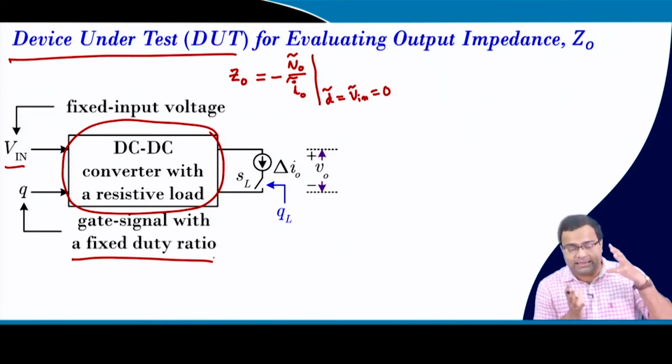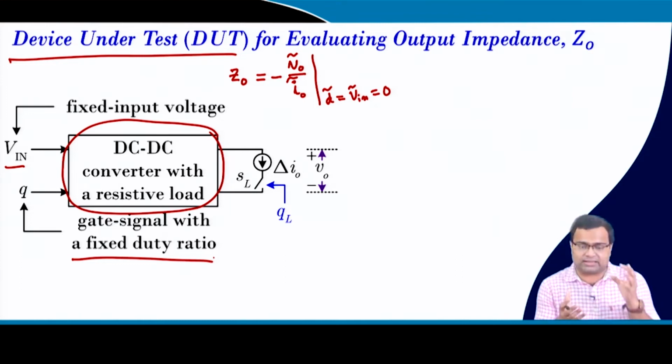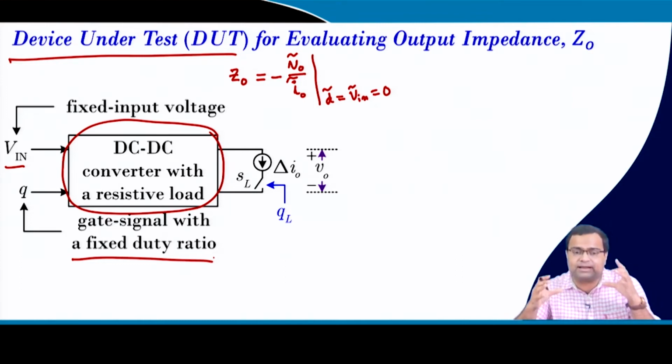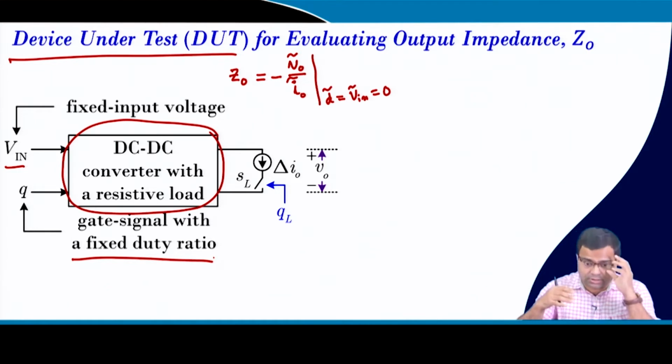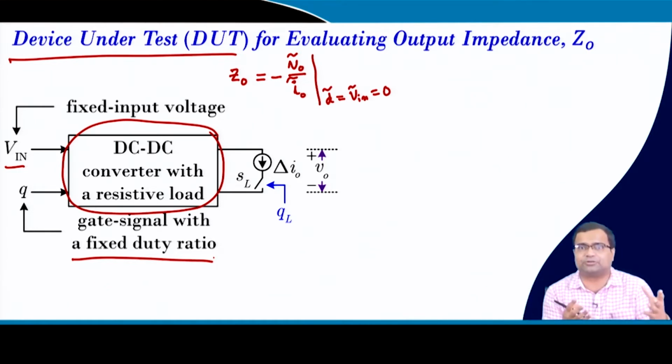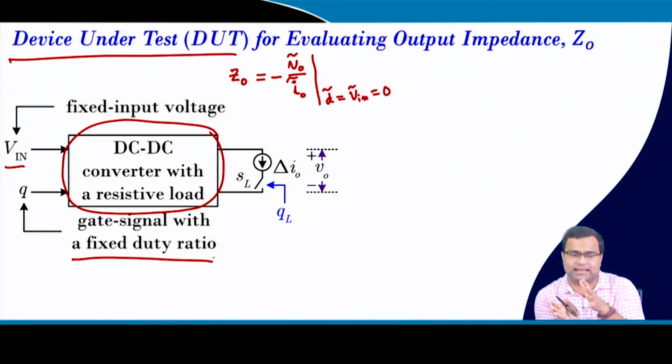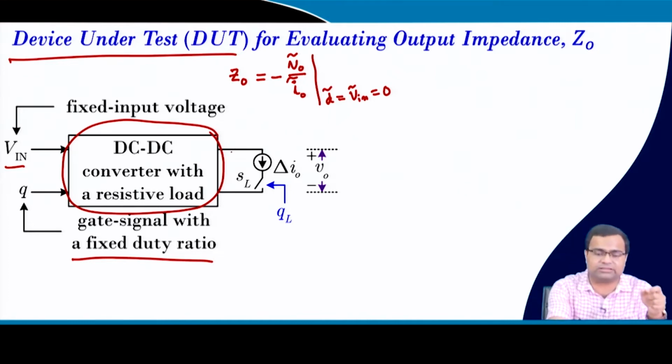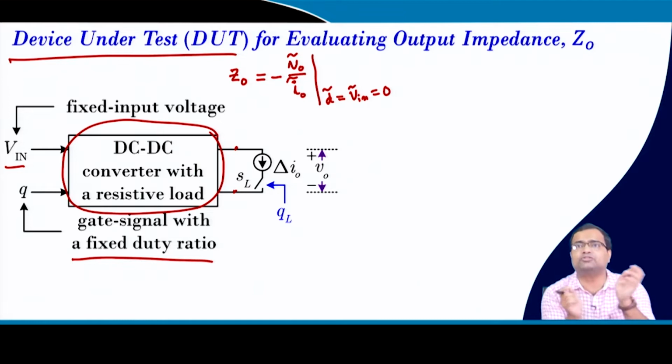Then in this converter, in fact in lecture number 13 we talked about the output impedance of a practical voltage source, right. So, if you take a power supply from the laboratory and you want to measure the transient response, or the frequency response of the output impedance, what can you do? For the power supply, only the terminal points will be available.